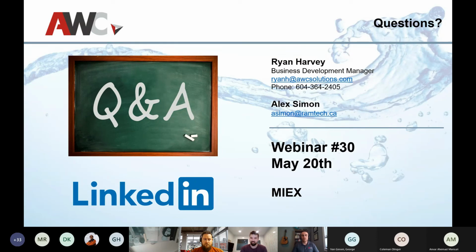Great. The next question is, what would you take into consideration to decide whether or not to use open or closed channel UV? Yeah, good question. Just for time, we didn't get too deep, or deep at all, into closed vessel UV. It is really effective if you want to maintain your pressure. So if you have an MBR plant, we often see closed vessel UV systems installed at the end of MBR plants, just so you can keep that pressure going right to your discharge.